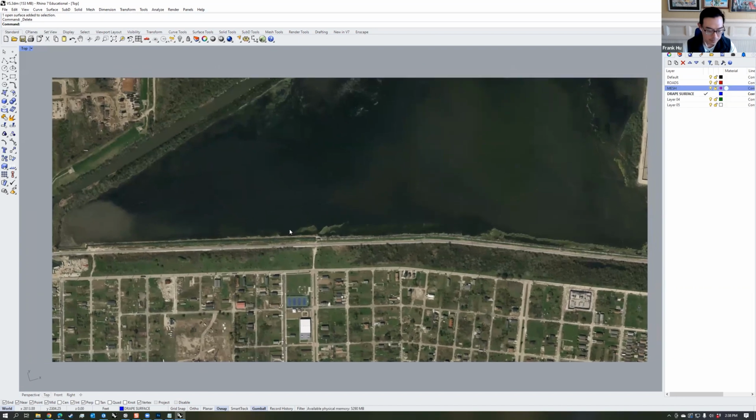If you type in drape one more time, you see spacing is set to 5. You can make that smaller. And so you can basically adjust the resolution of this surface. So if you choose maybe 2, that will increase the resolution of the surface.